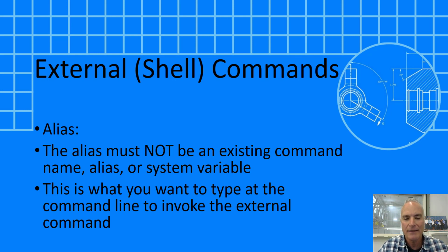So the alias, a couple things about it. It must not be an existing command name or an existing alias or a system variable. And remember, it's what you want to type at the command line to invoke that external command.